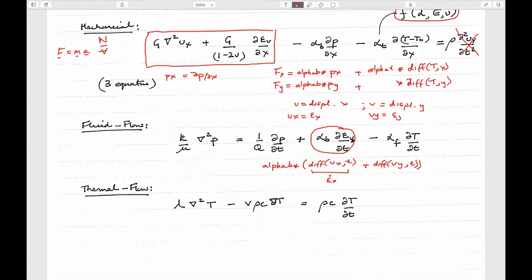And so this would be the effect of how much fluid gets squeezed out of the system by applying deformation to it. You squeeze the sponge. And so those are all things that we talked about in terms of hydromechanical coupling. But now we said, well, we want to make life even more interesting for ourselves by adding thermal flow into the system. So the equation that represents thermal flow is this. It's missing one term.